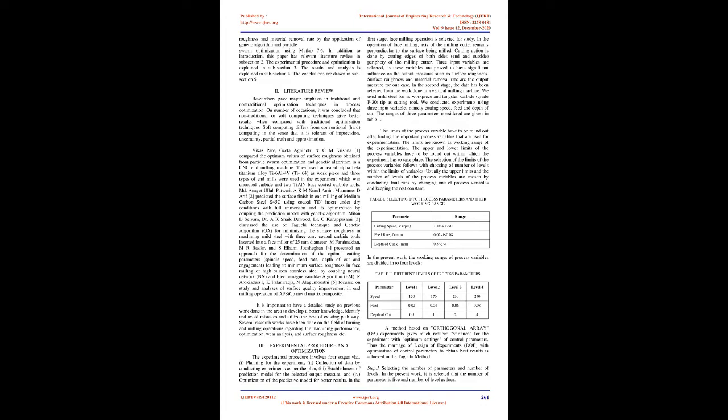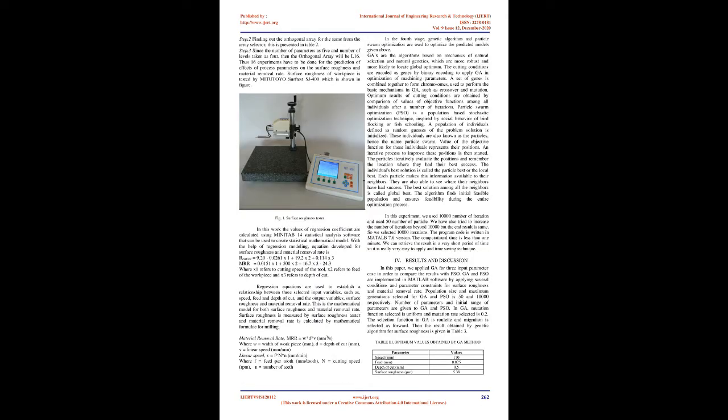M. Farahnakian, M.R. Razfar, and S. Elahi Joshegan [4] presented an approach for the determination of the optimal cutting parameters, spindle speed, feed rate, depth of cut and engagement, leading to minimum surface roughness in face milling of high silicon stainless steel by coupling neural network (NN) and electromagnetism-like algorithm.